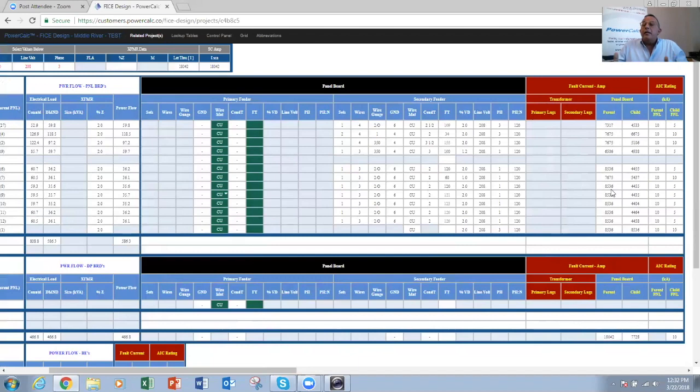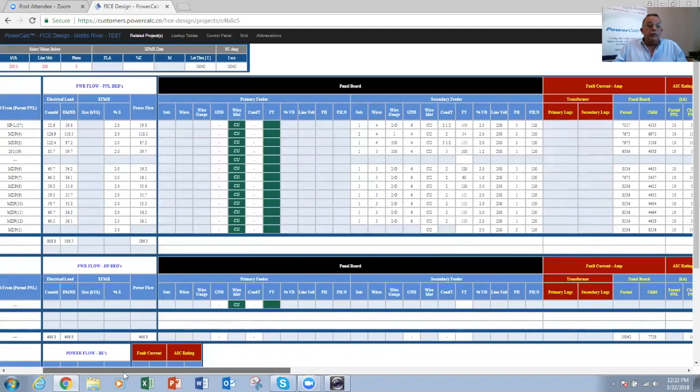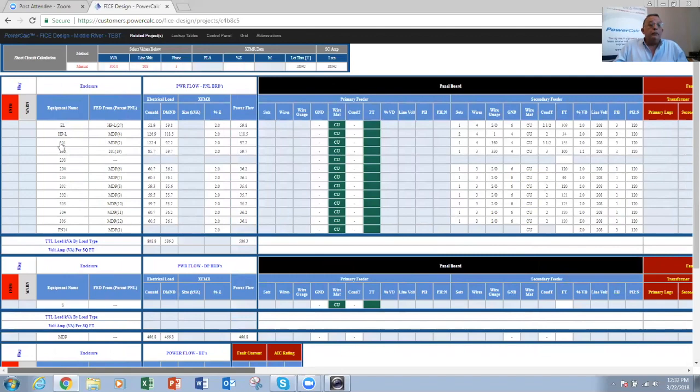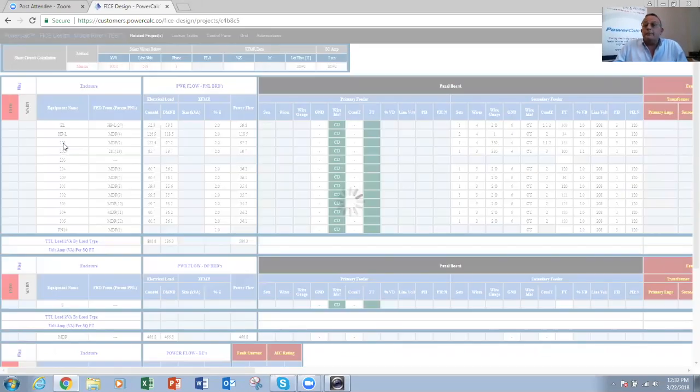Now, if any of the related parameters have changed, meaning if the input transformer value has changed from FPL, or the MDP feeder has changed, or you increase the load on panel 201 or panel 202, all these values are going to automatically adjust for you, and then adjust the AIC ratings automatically and display them on the panel. So where does this information get displayed on the actual panel? If we go to the panel, say again, since we're working on panel 201,